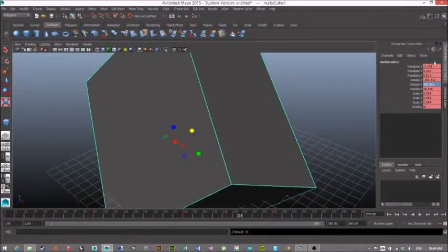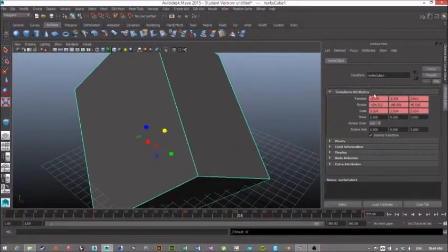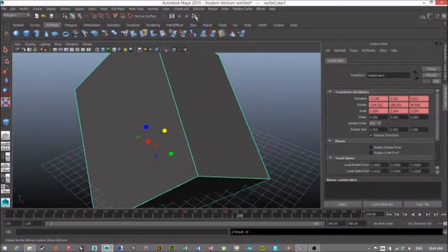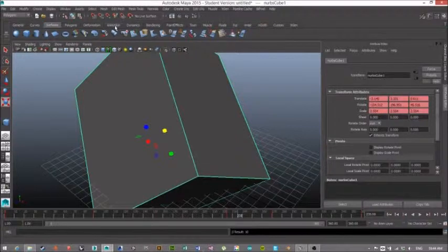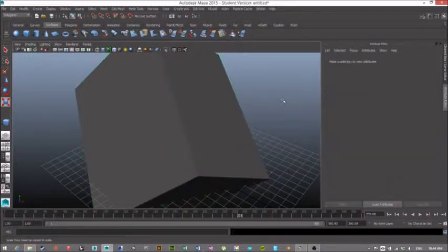Remember how we looked through the attribute editor last time? These keep getting built up and built up as you start applying operations. Every single thing with a number, all the way through into the rendering editor, every single setting, everything in here can be keyframed. So at the end, your time slider, if you were to select the entire scene, might be completely red at the bottom, just with little ticks of different lights coming on at different times and sun and stuff like that. What is nice though is if you only select one piece of geometry, those will be the only keyframes that show up. So you don't have to deal with all of them at once, only the geometry or the camera or whatever you're dealing with will show up in the keyframes.